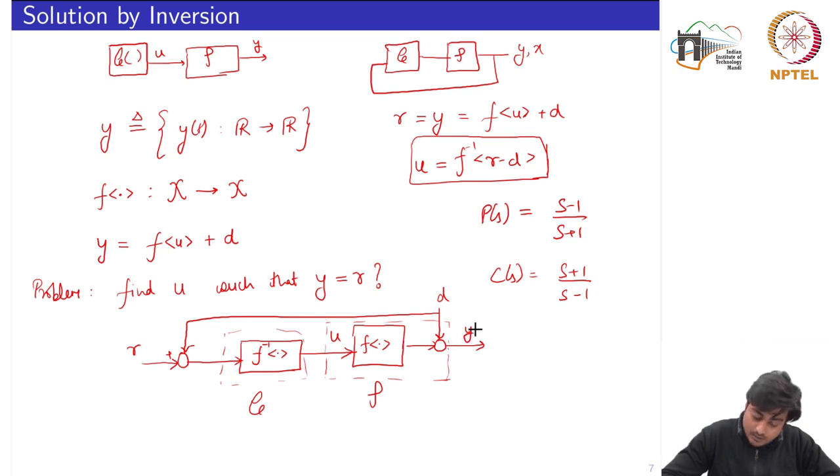So this is the major problem here, that the controller subsystem requires the inverse of the plant itself. Second, for computing the output of the controller, it requires the information of the disturbance variable, because the disturbance variable is being fed back to compute the control signal. In usual practice, we do not have the availability of this disturbance variable, and if the signal is not available to us, it is quite difficult to compute the control signal.